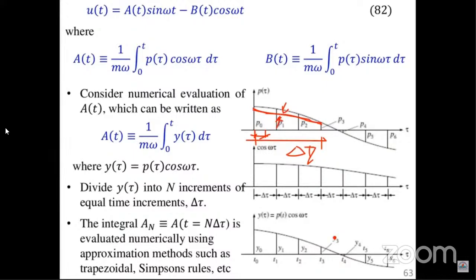You can have as much rest time as possible so that you can have your solution. This is the same case with numerical analysis, the finite element analysis that we used last semester. The same numerical analysis software we can apply in this course, dynamic analysis. So we talk of refining the mesh size, reducing the element size, so that we can have our answer converging as close as possible to the actual solution.